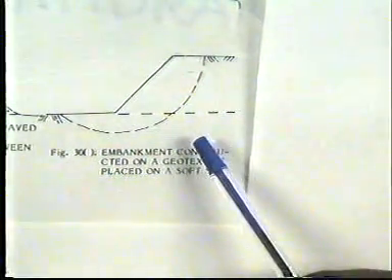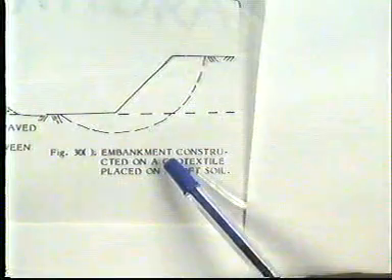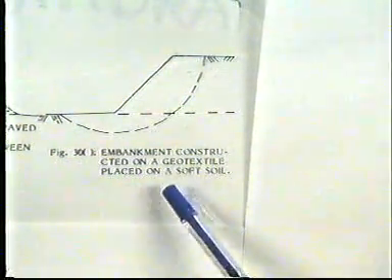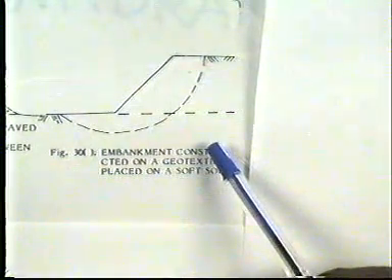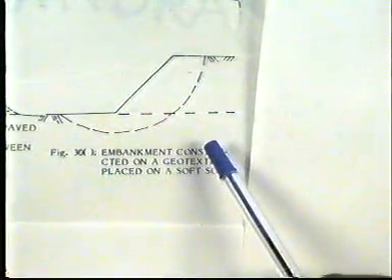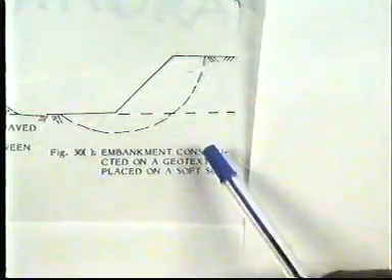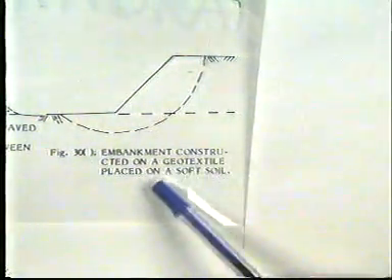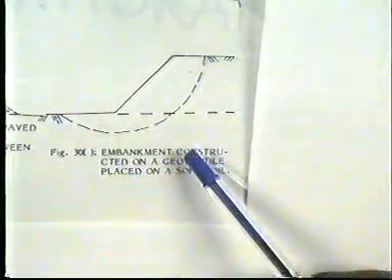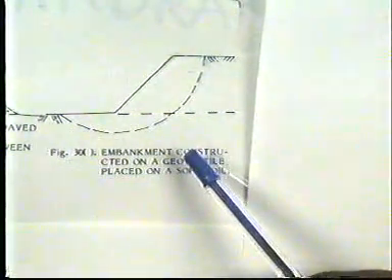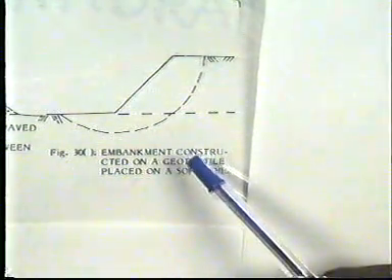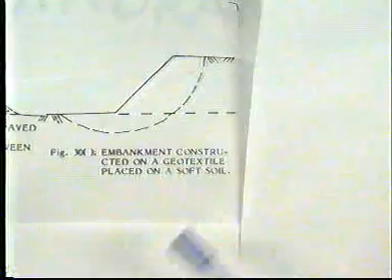So a geotextile functions as a reinforcement when it improves the mechanical behavior of an earth structure, through its tensile behavior when interacting with the soil through interface shear.